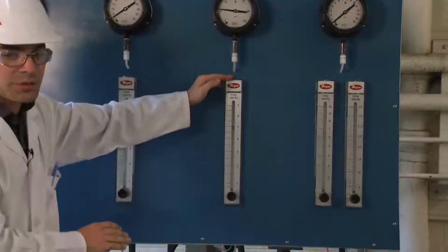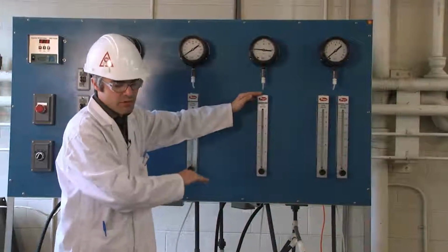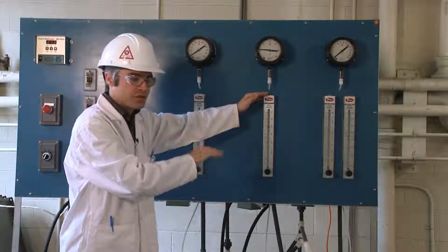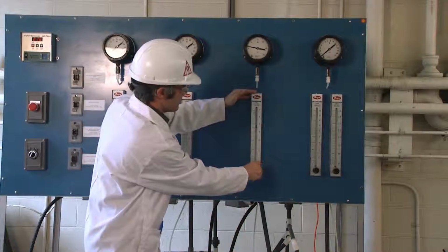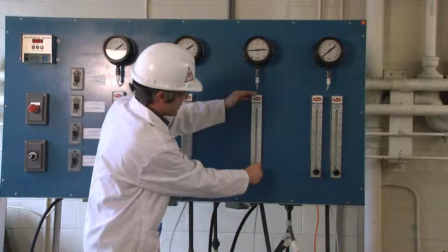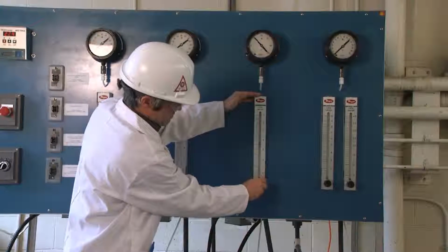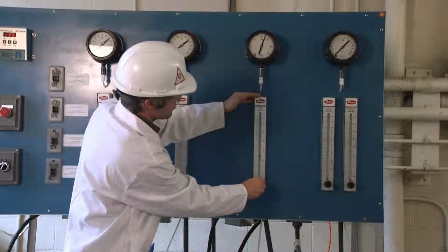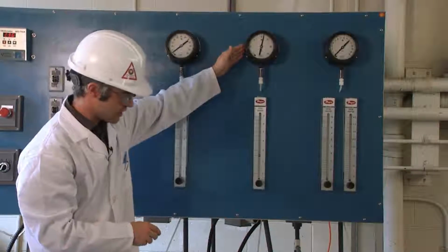This pump, due to its internal design, will be very good for certain flow rates, however will begin to taper off as you approach a specific flow rate, which you may or may not see in this experiment. Look for the reasons for this in the literature and attempt to compare to what you see during the experiment. Remember to set a flow rate, then look at the associated pressure.